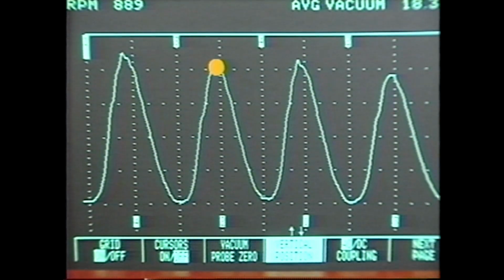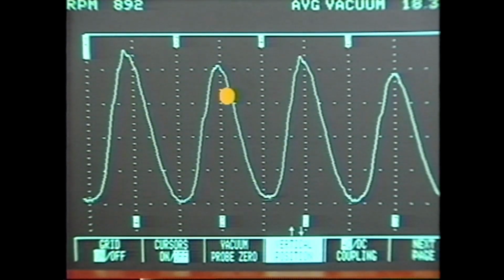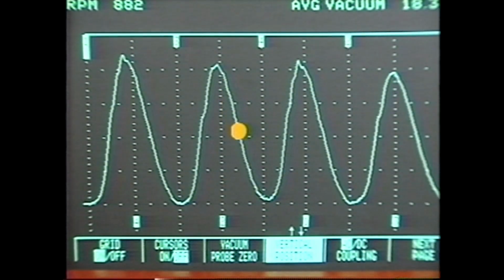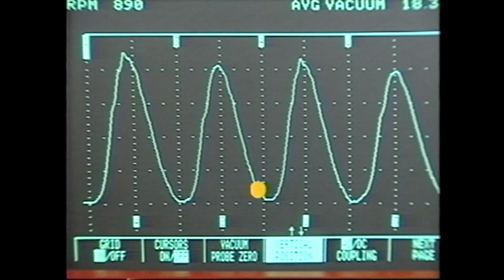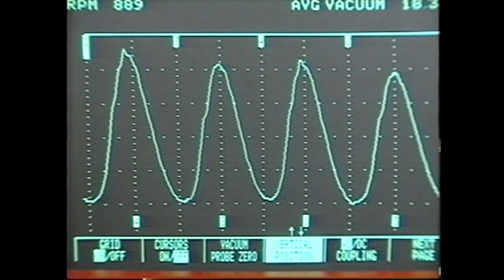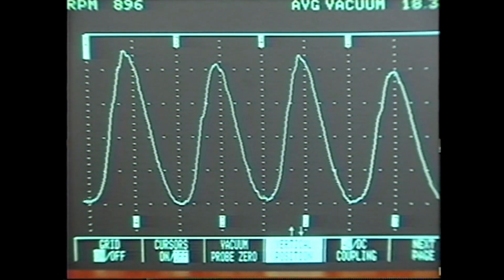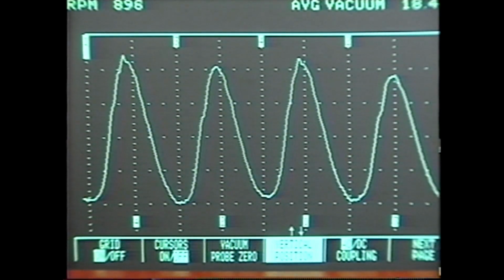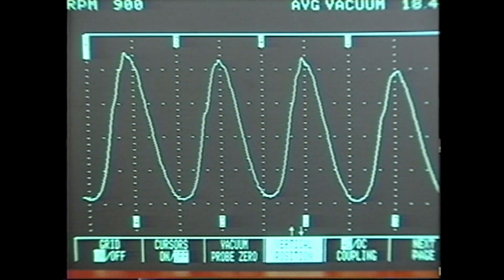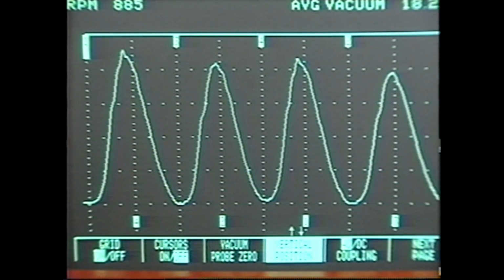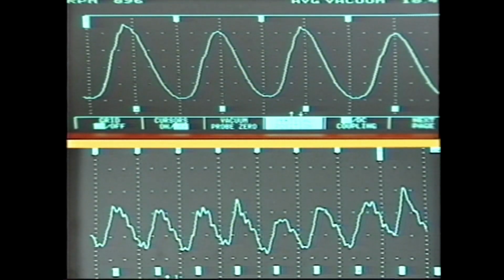The pressure in both the cylinder and intake manifold drop during the intake stroke, while the cylinder is drawing the air-fuel mixture in. This drop continues until the intake valve closes. The point where the valve closes doesn't show up because the next cylinder has already begun its intake cycle. The next cylinder will begin its intake stroke before the previous cylinder's intake stroke is finished. The amount of overlap depends on the number of cylinders.